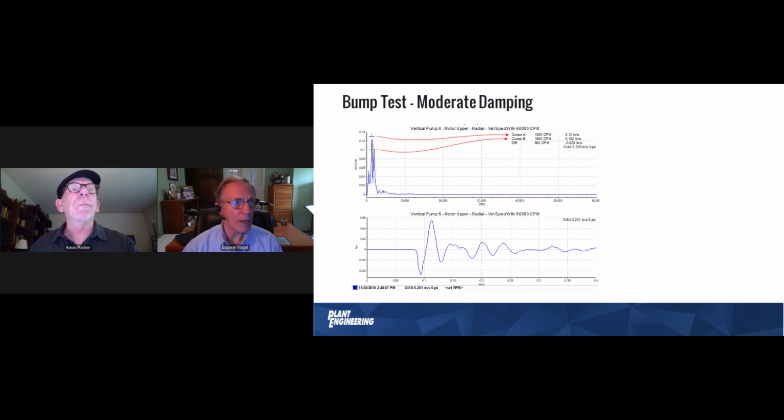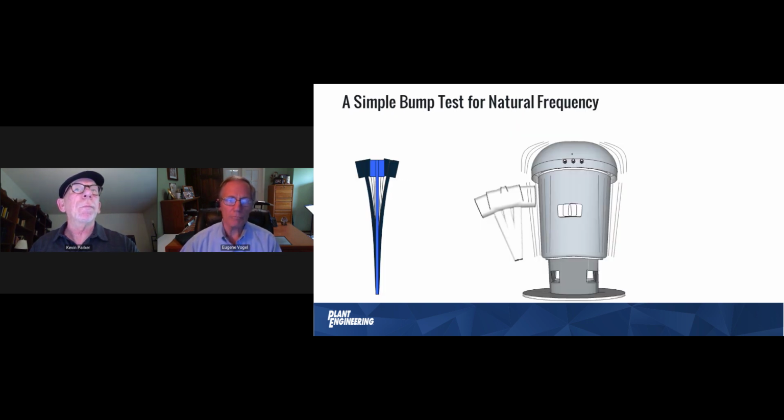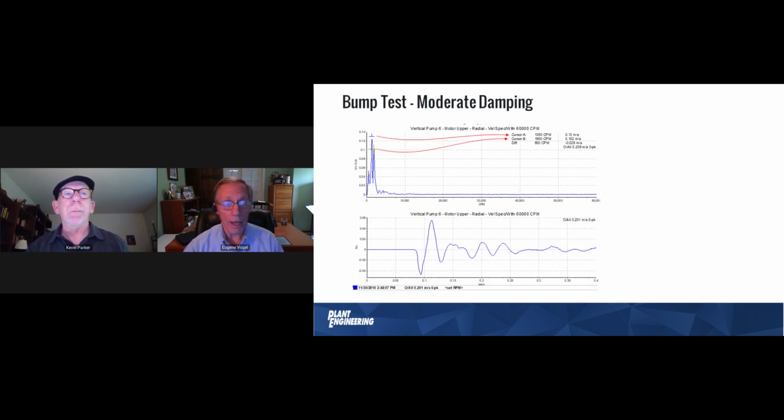And let's, for the sake of simplicity, assume that's our machine, okay? So I went out and I gave it a wallop with a mallet. I go whap. And just as if you hit the railing on a stair, and it went, okay? Well, the machine does that too. You may not notice it right away, but if you put your finger on when you hit it, whoa, I could feel a little bit of vibration there. So if you could feel a little bit of vibration on your finger, then the vibration transducer will take that vibration and show you what it is.